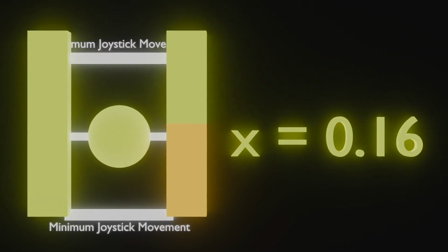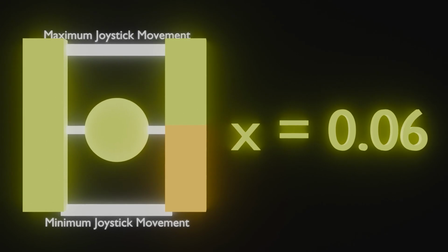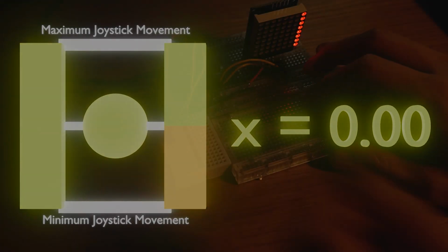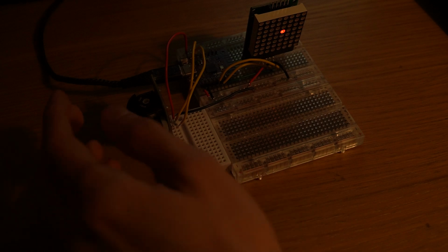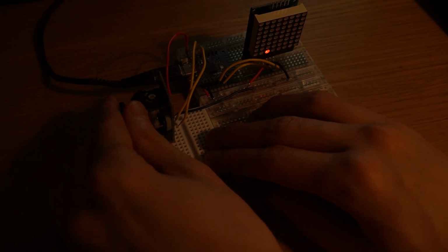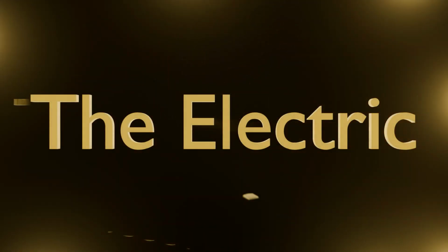But if our starting voltage is different, then the output will be different as well, even though the joystick position didn't switch at all. And that's why we need to switch from 5V VBus to a 3.3 on the other side, to keep the output consistent and keep it centered so that when the joystick is in the middle, we get the right voltage. And so there, I've already done it previously, that's why the dot worked so well, but still I feel like I should have mentioned it. And now with that in mind, we can safely move on to